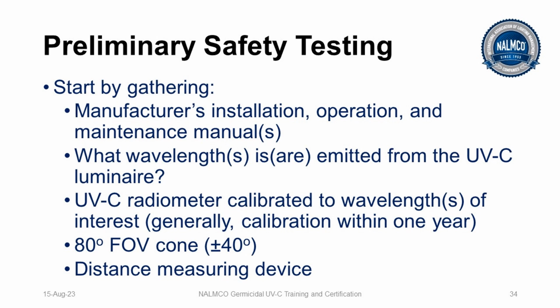Generally, meters are calibrated every year. I often calibrate them every 2 years, but I stagger them, so I always have 1 meter that's within 1 year of calibration. If there starts to be significant deviation between the two, then I will need to send them back in for testing and calibration.